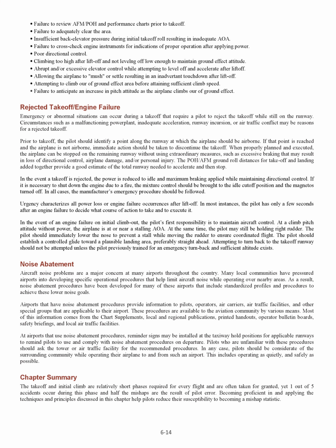Urgency characterizes all power loss or engine failure occurrences after liftoff. In most instances, the pilot has only a few seconds after an engine failure to decide what course of action to take and to execute it. In the event of an engine failure on initial climb out, the pilot's first responsibility is to maintain aircraft control. At a climb pitch attitude without power, the airplane is at or near a stalling AOA. At the same time, the pilot may still be holding right rudder. The pilot should immediately lower the nose to prevent a stall while moving the rudder to ensure coordinated flight.